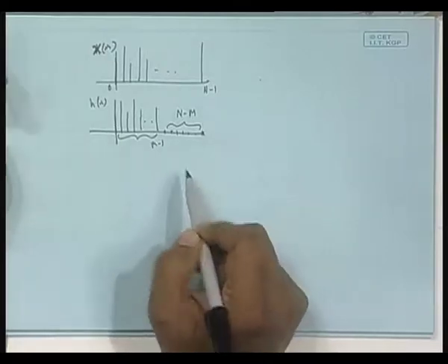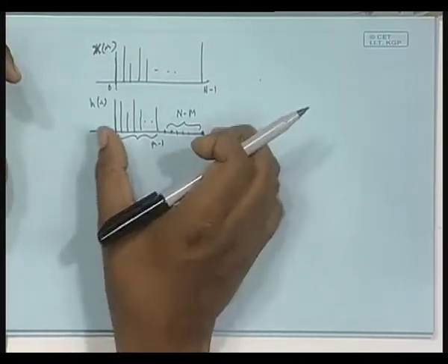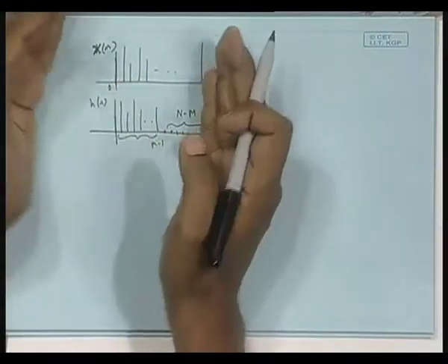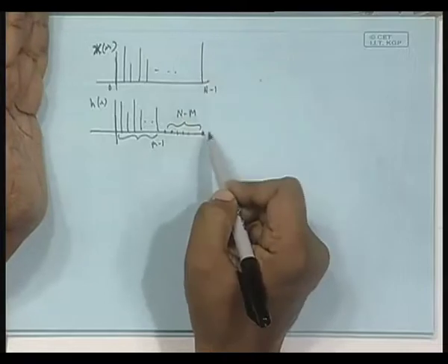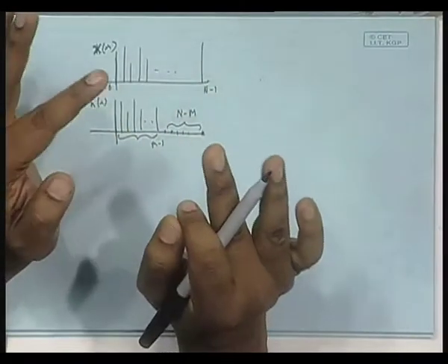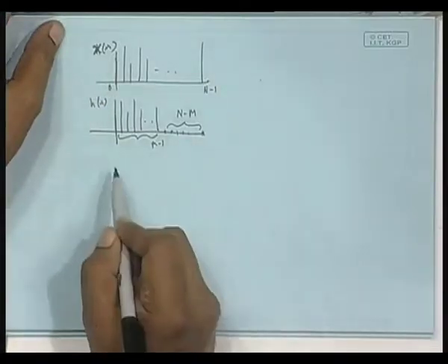So, suppose I do the circular convolution. I will be making a periodic version of it, reversing it, and then applying 0 shift, first shift, and so on, always chopping off portions to the right of n minus 1 and to the left of 0, doing sample-wise multiplication of top and bottom and adding. That is a simple follow. So, if I do that,